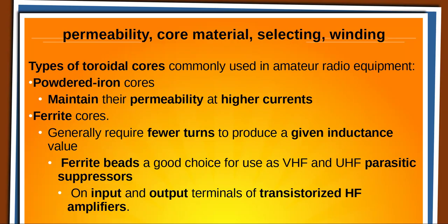So you can kill a ferrite toroid. That's why with chokes, and particularly matching transformers, when you're sending 1.5 kilowatts through it, you've got to ensure that you have enough core material to handle the flux, because it heats up. If it isn't a big enough toroid, you're going to overheat it and it's no longer going to work.